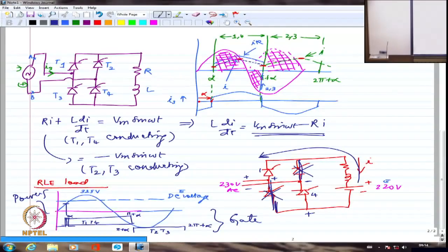That's what we did. You remember, we ANDed it with high frequency and then we made the amplification, and after the amplification in the collector we had connected a pulse transformer. That's what we had done. So please correlate these two. We are having a pulse given here. If I am having one pulse here, it is not going to allow the SCR to fire, especially under discontinuous conduction. So I might have to give it a fair chance to conduct by giving a wider pulse.